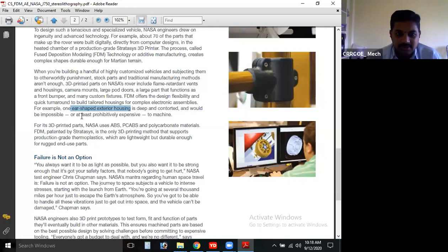So they are developing these 3D machines day to day to produce components. For metal components, the major drawback of 3D printing is that it takes much time, even though the component is small. Whereas in subtractive manufacturing, if you want to drill a hole, we just program the CNC machine and it drills or grooves into the object. So it takes very little time.